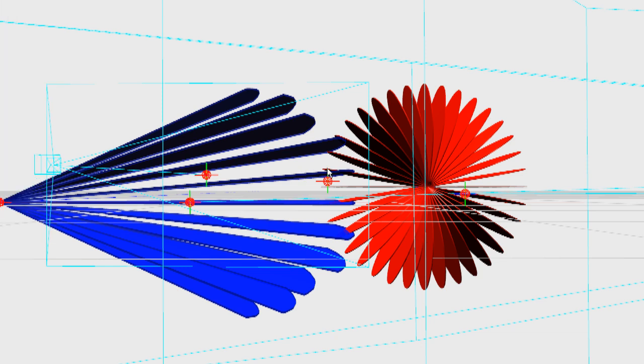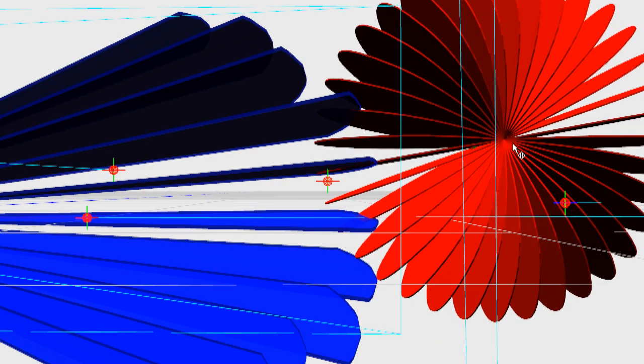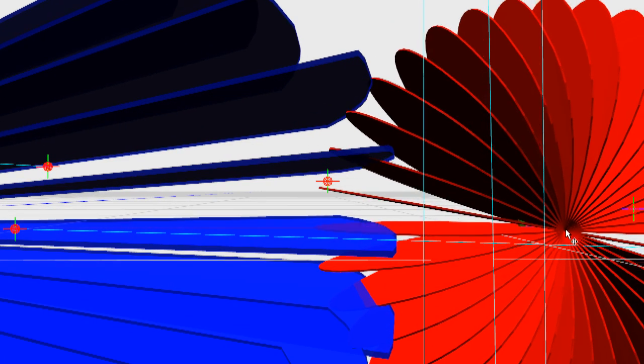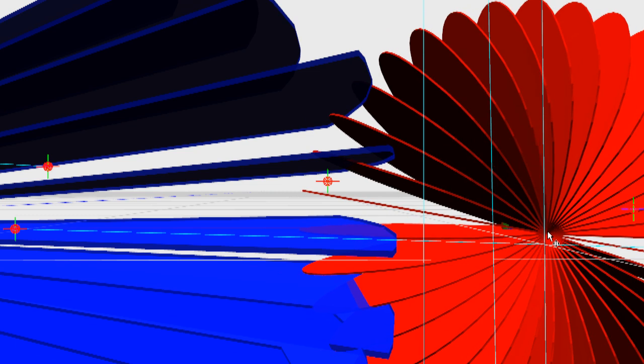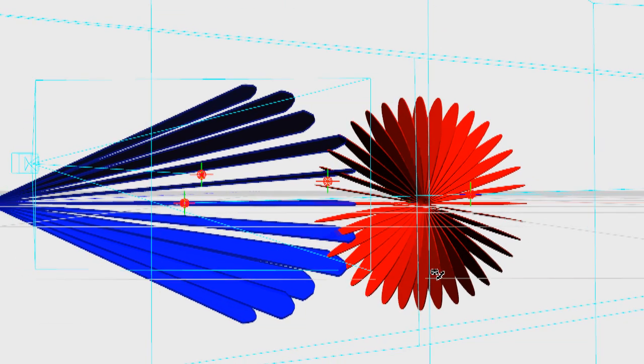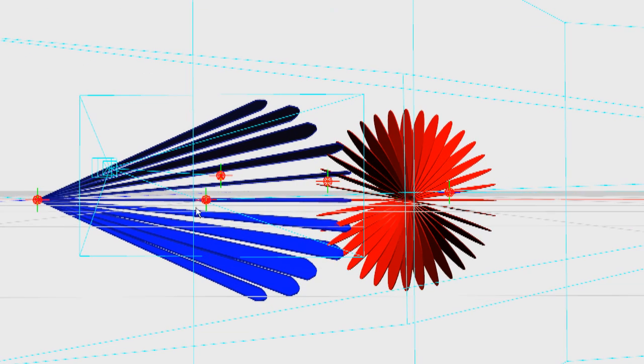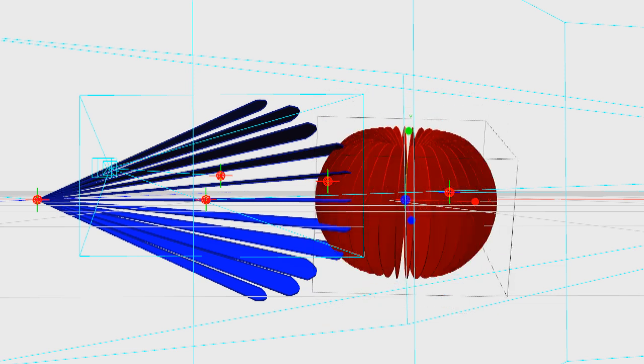So again, as we turn into a turn, the horizontal polarized antenna is going to be the one that your receiver chooses because it's got the biggest cross-sectional view. And that's all a diversity receiver does, is it looks at both of the signals coming in from each of the receivers and chooses the one that's strongest and switches to the one that's getting the best signal. So in this instance, the horizontal antenna is getting the best reception because our plane happens to be in a horizontal fashion. So let's return the plane back to straight and level flight.